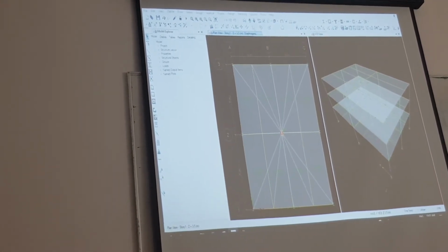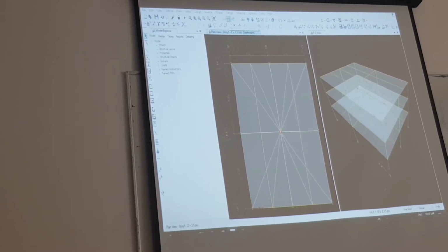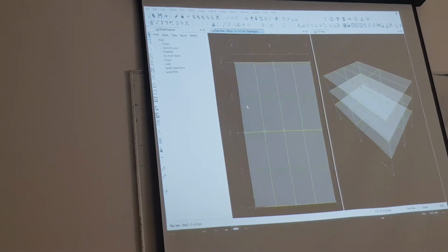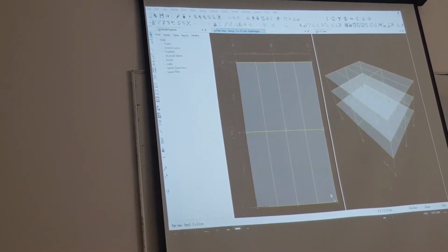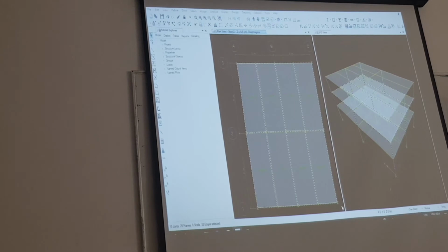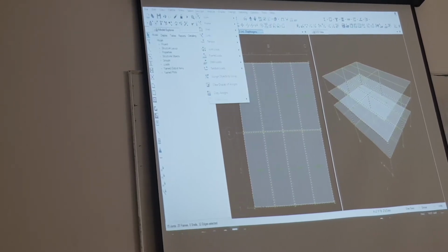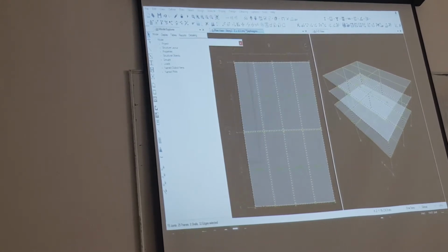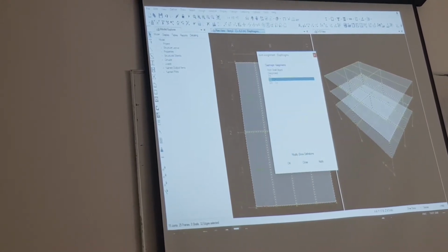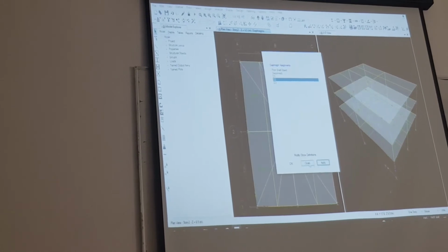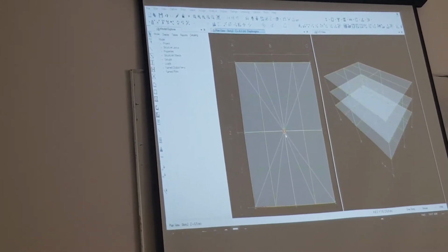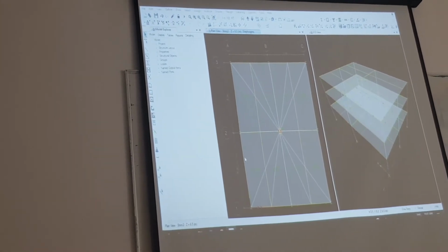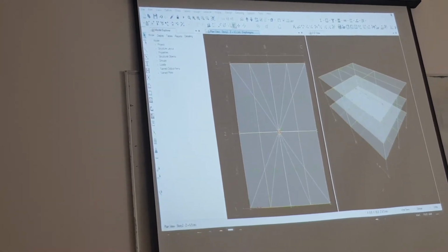Now go to the second story, go to the plan, select story 2. Again you are going to select all these members. Again, you are going to assign, following the same steps. Assign, joint, diaphragm. This time D2, apply. And again, the center of rigidity is at 6 meters from the x-axis and 8 meters from the y-axis.